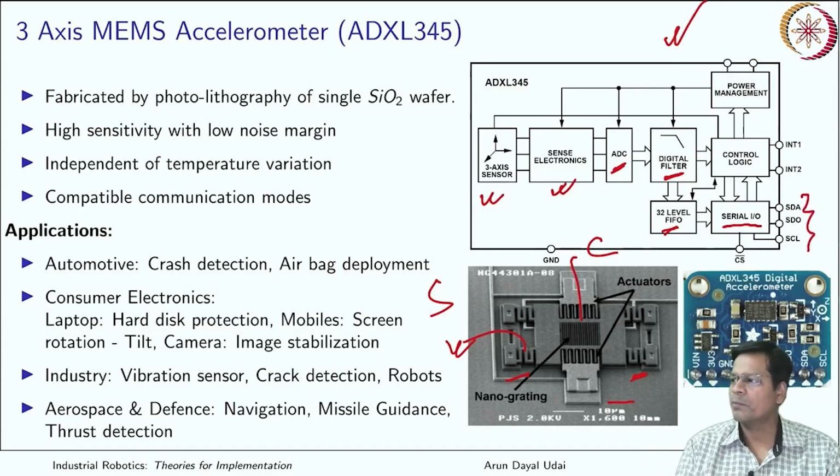If somebody has worked on embedded systems or even Arduino, they know it, actually this is I2C, two wire interface communication. You have a serial clock, you have a data line, and that is a circular buffer kind of thing that keeps on going input and output. So that works like this. It is master to slave communication sometimes, or sometimes it is just one-way communication like this device. You just send in the clock and you can keep reading the data which is there. Data may be 8-bit, 9-bit like that. Normally it is 8-bit.